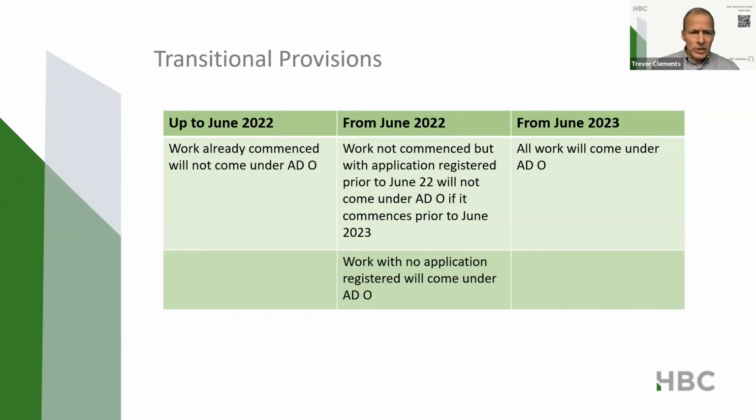So that commencement is all critical, and it's made clear that you can't just commence one unit on a development of say 100 houses and then get under the wire for Part O. The requirement relates to each and every unit, so you have to apply it in that way and commence every unit. And what does constitute commencement? Well, something like digging a foundation would, preparation of the ground for a raft foundation, that would be regarded as a commencement. Laying drainage, also, yes, but something like just a site strip or demolition of an existing structure on the site would not constitute a commencement. So hopefully that's reasonably clear. And you know what you've got to do if you want to try and miss the regulations applying.